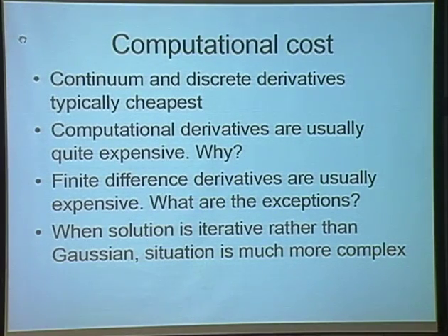But there is another reason, and the reason is that those programs are blind and they sort of calculate the derivatives of every line on your computer program, whether you need it or not. So it's sometimes difficult to tell it to be frugal. Finite difference derivatives are expensive. If you have 1,000 variables, and for each variable you do a new analysis, then calculating derivatives will cost you 1,000 times more than a single analysis.